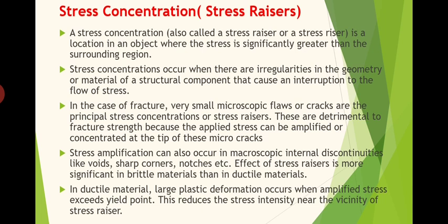See, if a crack is there in a ductile material, once we apply a particular stress on a material, say sigma A, the applied stress is sigma A. If voids or microscopic cracks or flaws are there within the material, at the tip of that crack the ductile material also will be experiencing this same magnified stress or stress concentration.